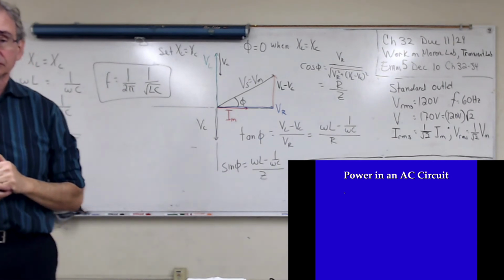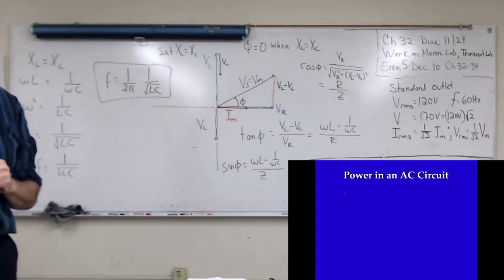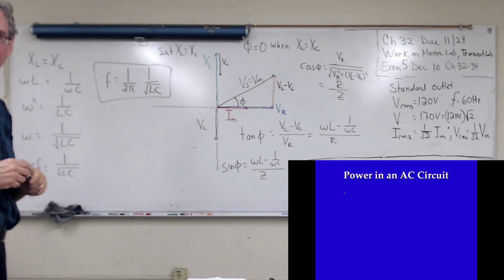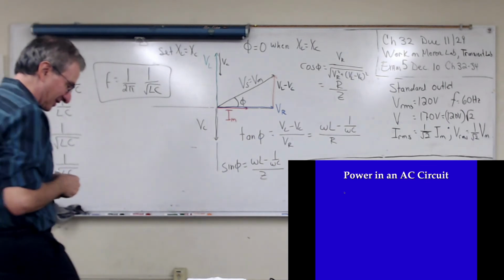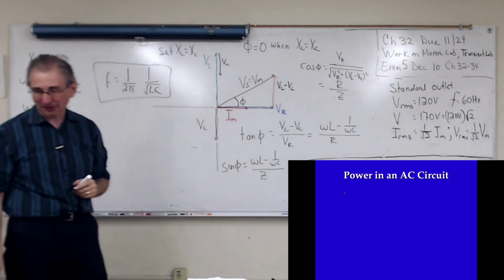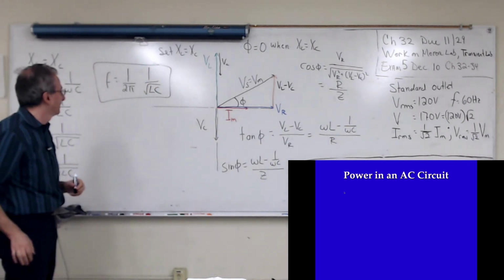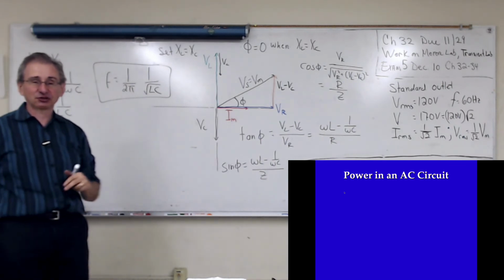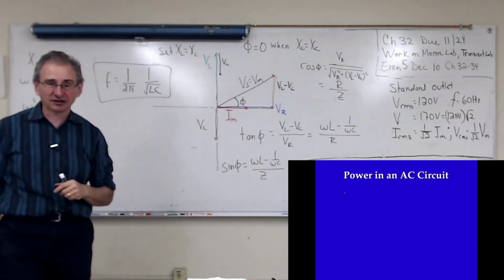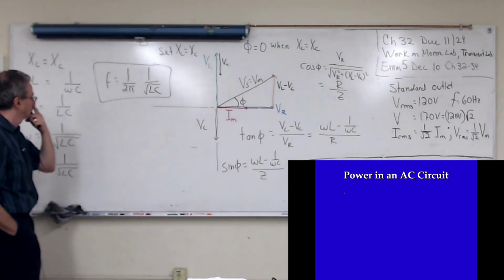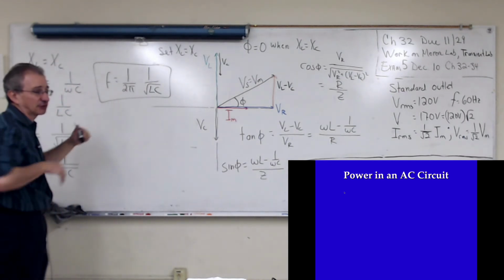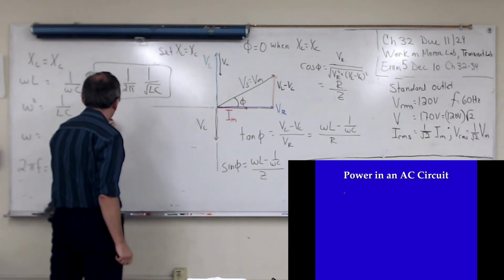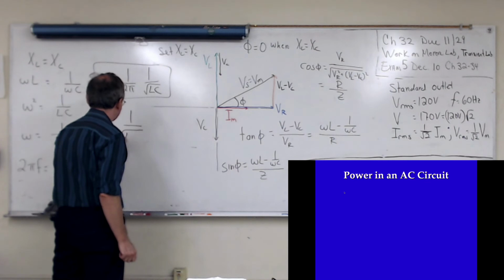I've seen that before somewhere. Yeah, when we did the LC circuit, right? We did the oscillating circuit in the previous chapter. That's kind of why we talk about that. We talk about it because that comes up often. And we also saw when I did the RLC transient response, you saw that product also. So this is called a resonance frequency, and a lot of times you write f naught, or omega naught equal to 1 over the square root of LC.